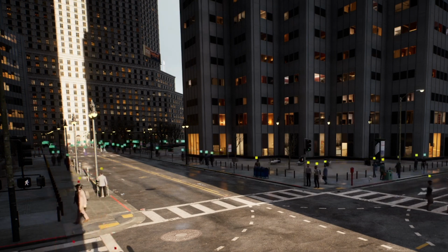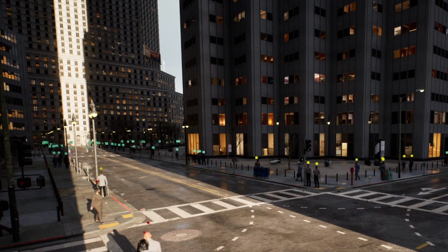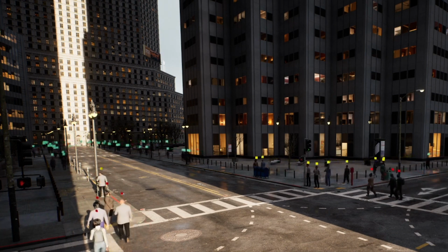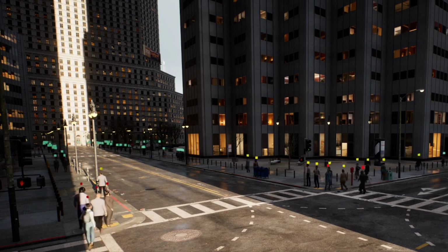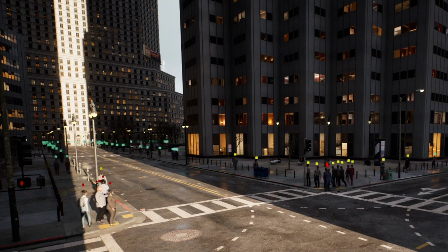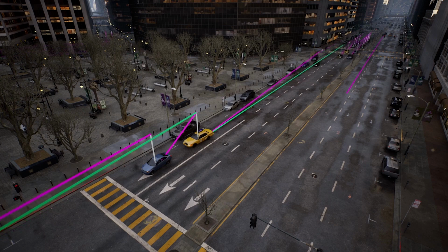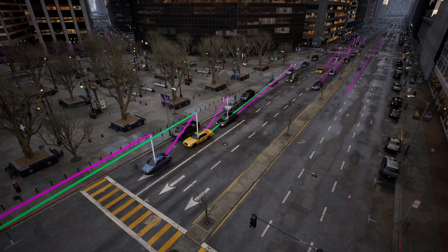And finally, it allowed for smooth animation transition, even when switching from a vertex animated mesh to a full-fledged actor, since the runtime animation data was persisted in the animation fragments. For the traffic, rather than using a state tree, the behaviors were all programmatically made in Mass processors, which is to say that the framework does not constrain you to one approach over the other. The most typical behaviors were follow on lane and wait at the intersection.